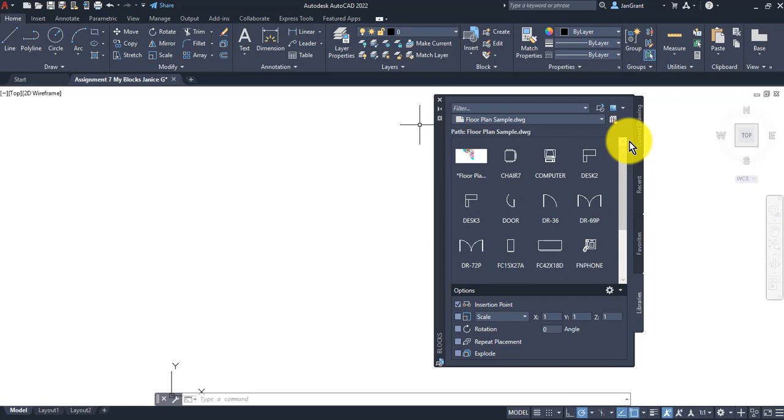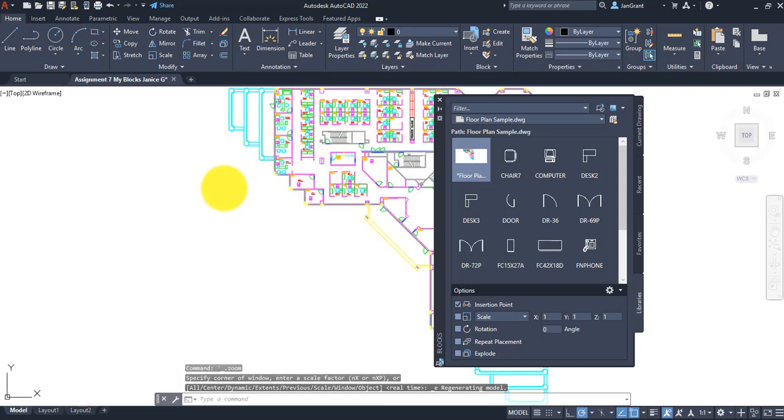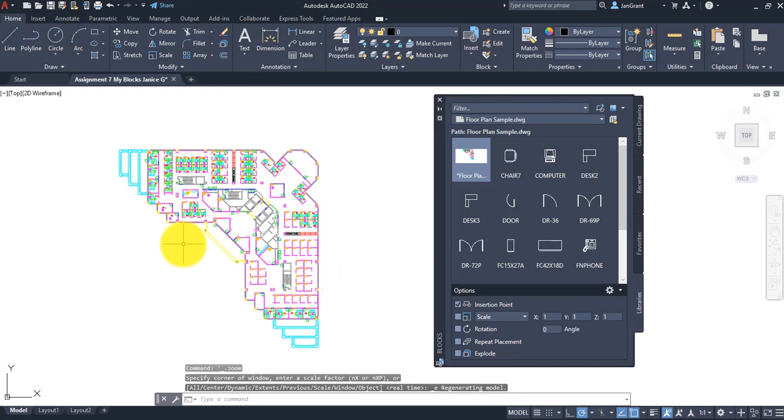So we want to make sure that instead of bringing any of these other blocks in, we're taking this drawing right here, and we're going to hold your left mouse button down on it, pull your mouse out, and let go. Now it doesn't look like anything's been brought into your drawing because we're zoomed down really close. We're only in this small little, I think it's 12 by 9 inches section, and the drawing's way out there somewhere. So double click on the wheel of your mouse or do a zoom extents, and there's the drawing.